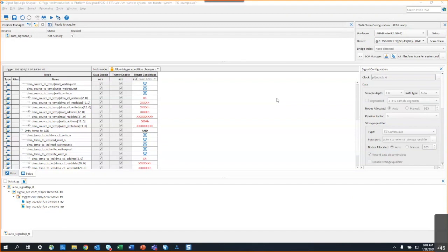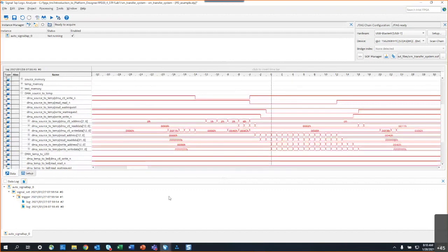When SignalTap captures data, it gets stored in on-chip memory on the FPGA, and then that gets transferred over JTAG so that you can see these lovely waveforms of your data. We do have other tools that do live trace, like the In-System Memory Content Editor to monitor the contents of on-chip memories, and In-System Sources and Probes, which is like sticking an LED on a point in your design. But no, SignalTap does not do direct data tracing. JTAG's too slow for that.